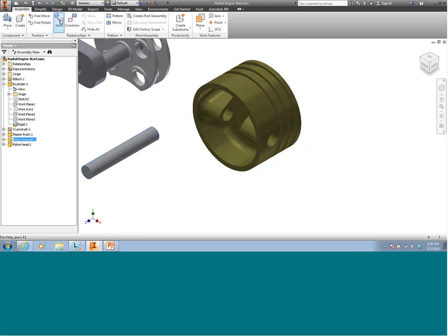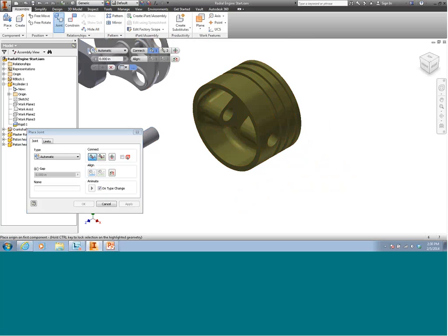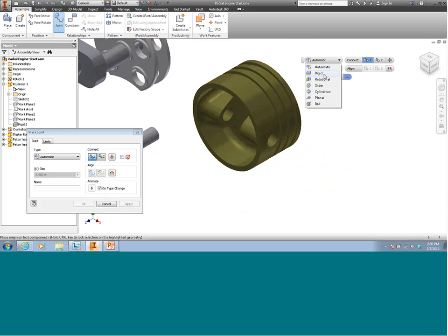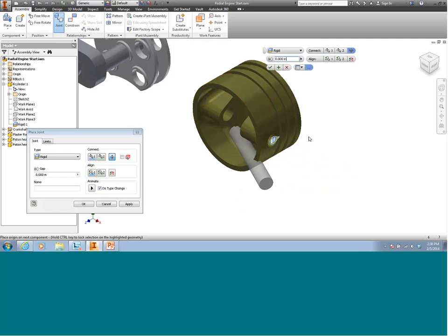And I've just hit escape, which is what takes me out of the command. So I'm just going to do this again quickly here. I'm going to assign my rigid constraint here and here. Again, it's going to flip it into position, and I'm going to enter my value.